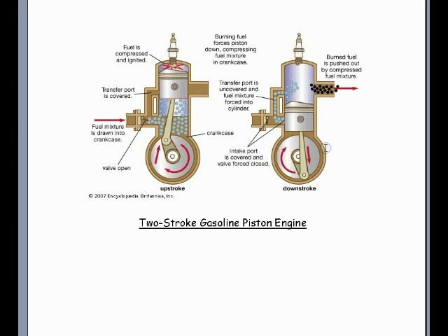The 2-stroke piston engine will reach its maximum rated brake horsepower and torque at maximum RPM. As a matter of fact, the correct way to operate a 2-stroke gasoline piston engine is to operate it at maximum RPM at all times, because higher RPM equates more lubrication of the crankshaft, piston rings, and connecting rod, as well as increased airflow through the cylinder for cooling.